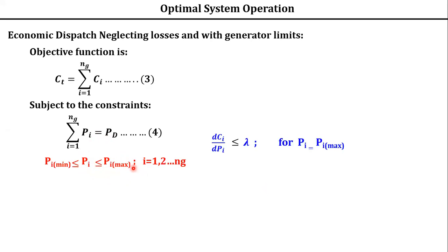So what should you take? The calculated value is 110 megawatt, but the maximum value is 100 megawatt. Therefore Pi must be operated, or pegged, or clamped, at which value? Whether it should be operated at 100 megawatt or 110 megawatt. Hope you understood this example.